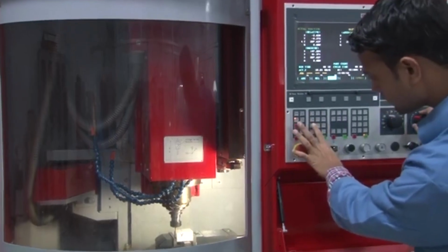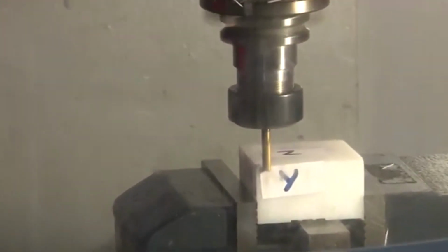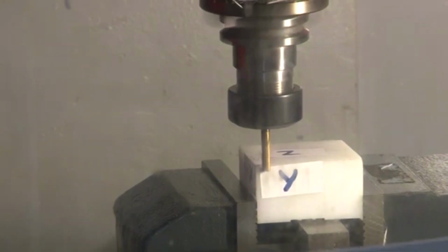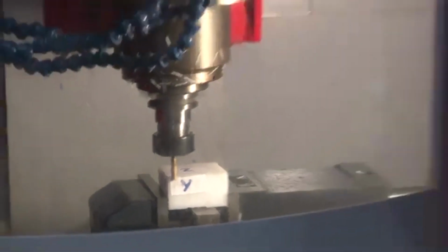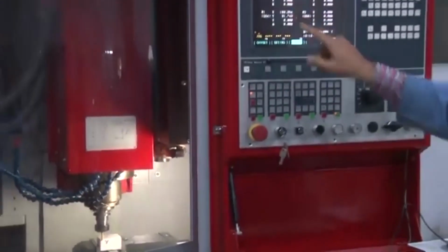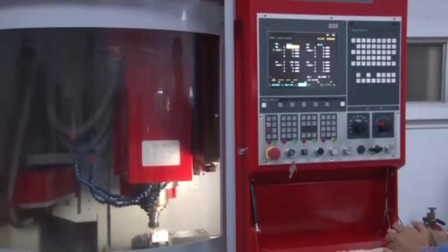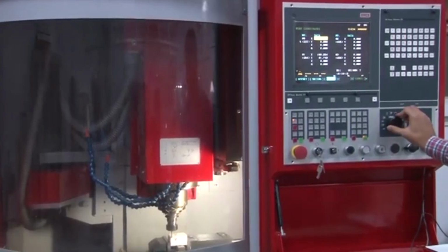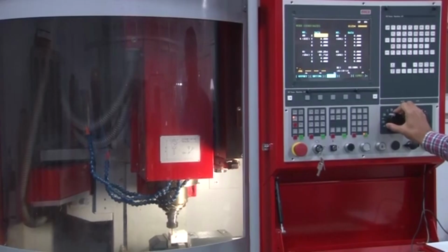At this coordinate, this tool is positioned at this moment. So, from the 0 position, the tool will take the dimensions as per the program, and when it is put in the automatic mode, you can see that the tool will automatically come to that position, and then it will move according to the program given there, along with the groove that it has to make, the circular surface that it has to make, and so on.